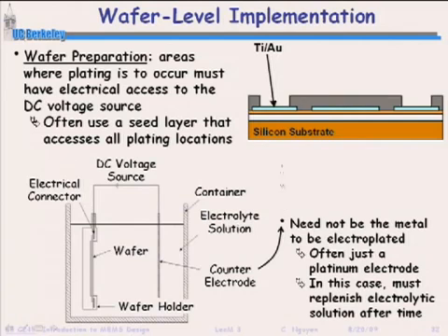But you'll notice that as you do this electroplating, the whole wafer is covered with a metal. That allows the current, which is necessary for electroplating to occur, to get to these portions here where electroplating occurs. You also see that you can't necessarily electroplate over every metal. There are different metals that you can electroplate another metal over.